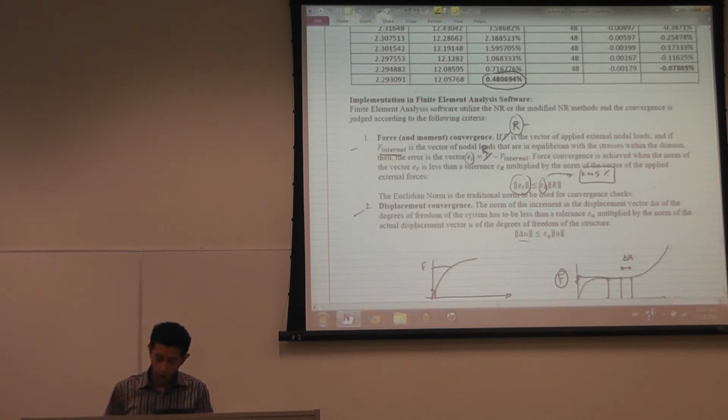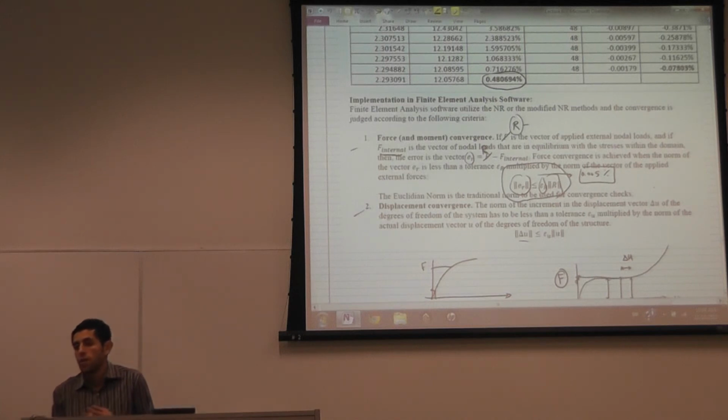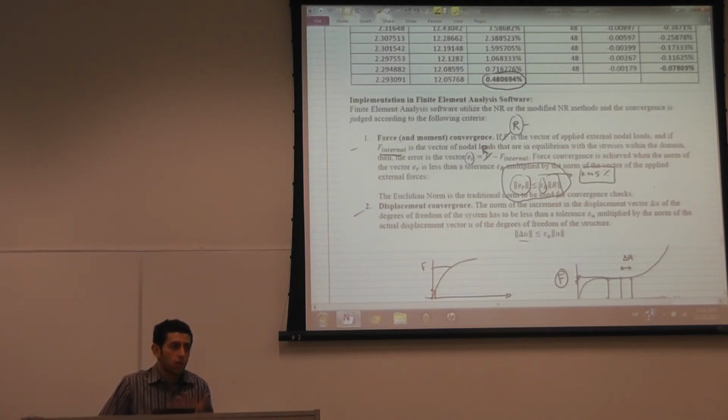And so this error was huge. 10 power negative 9, but 10 power negative 8 compared to 10 power negative 9 is huge, because the software does not look at it as 0. It depends on the numerics and the machine that you're using. If you're comparing 0 with 0, but they're not really 0, the software doesn't know what units you're using, whether this is Newton. All it does is compare the external forces, the residual forces, with the internal forces. So if I'm comparing 10 power negative 8 to 10 power negative 9, it's only 10%. So this is a huge error.